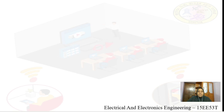SF6 circuit breakers use SF6 gas. Hence we saw its physical properties, its chemical properties, then its benefits, like it has a high dielectric strength and it can extinguish the arc at a higher rate. All these points we saw in the introduction to SF6 gas. Later we saw the different types of SF6 circuit breakers.